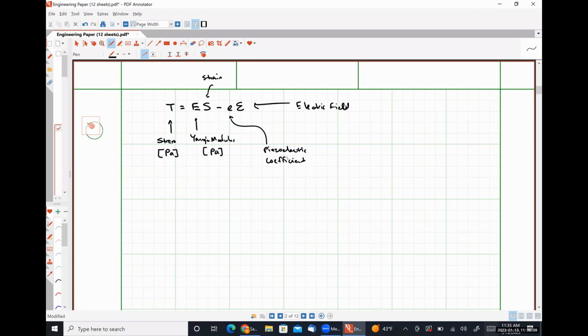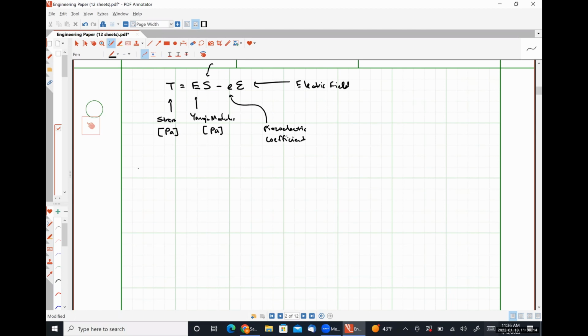All right, so piezoelectric materials are by definition anisotropic materials because they have to be polarized and they have to have asymmetry. So really these constituent equations are large matrix or tensor equations. That being said, the overwhelming majority of piezoelectric sensors are going to fall into one of two cases, either a longitudinal transducer or a transverse transducer. So we can simplify this math into something of a more closed form solution. So let's look first at the case of a longitudinal transducer.